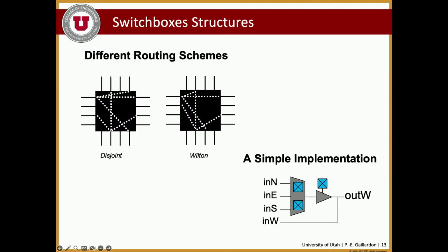If we just look at the low-level hardware, it's going to be, again, multiplexers, configuration memories, and that's it, right? So it's really a game of minimizing these resources that are extremely costly, right, at all times. And to do that, one of the techniques that is used is channel segmentation.